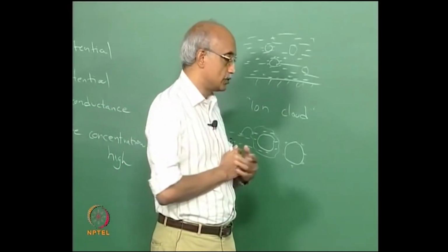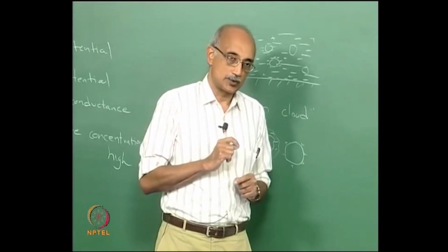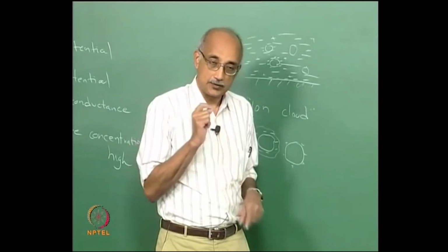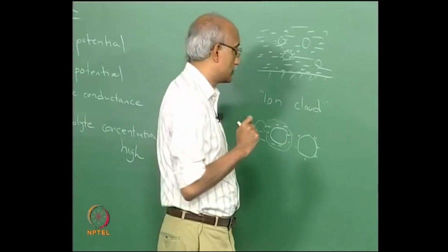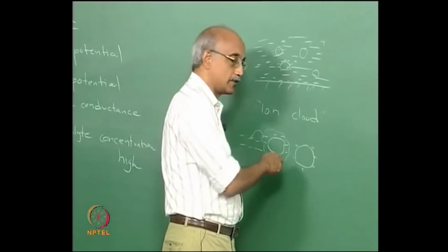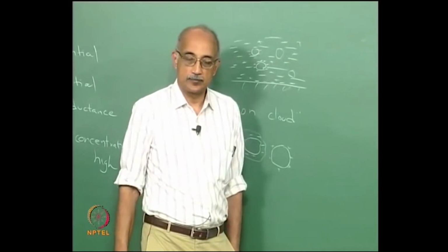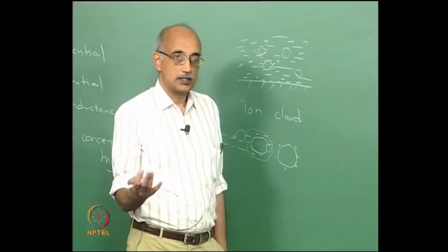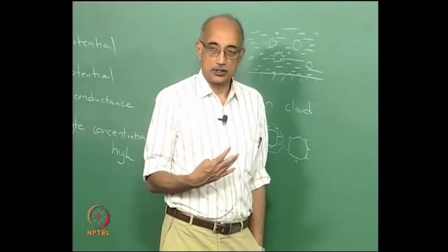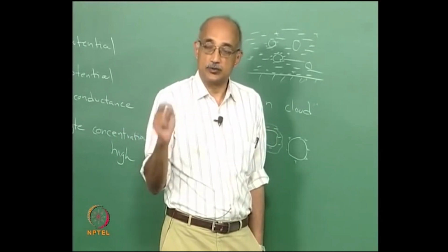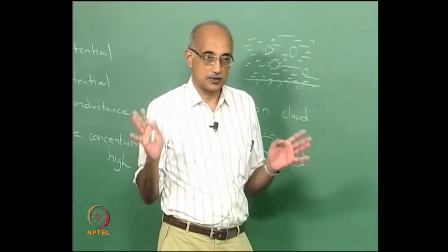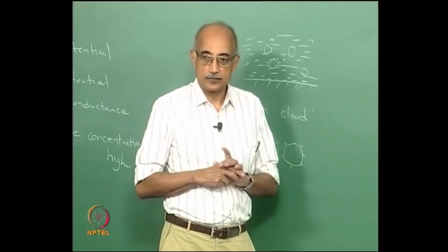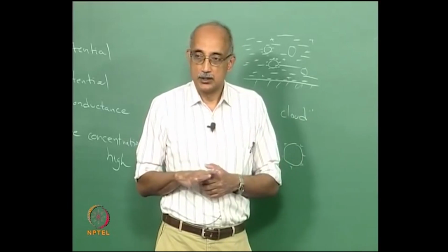Now, when you do this chemical mechanical planarization process, the size of the particle plays a huge role in its effectiveness. What can happen again, if you have high zeta potential in the system, depending on whether it's an attractive potential or a repulsive potential between the particles, is you can either get a well segregated suspension of particles in solution, which is what you desire really.